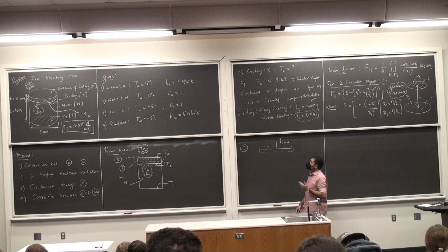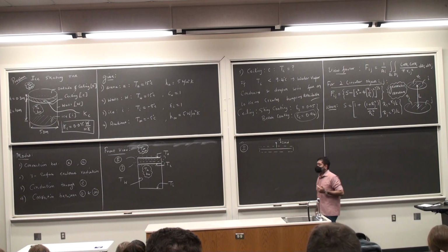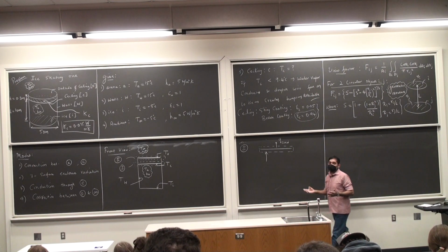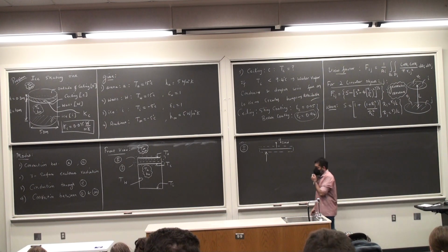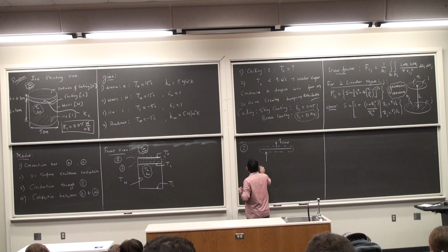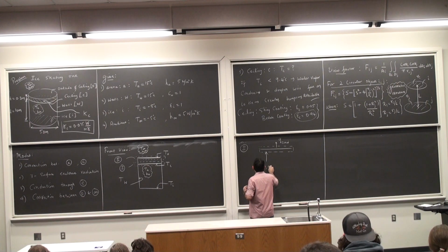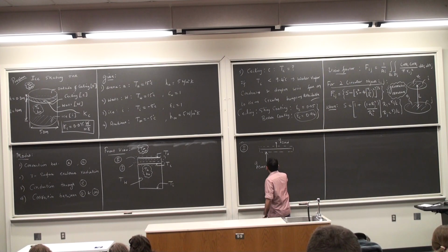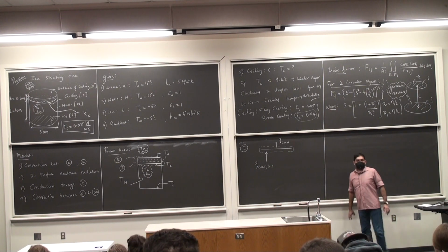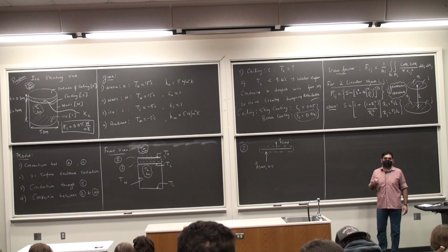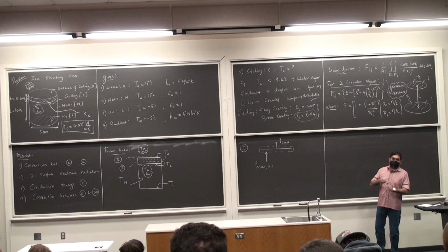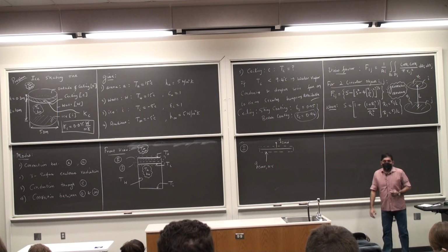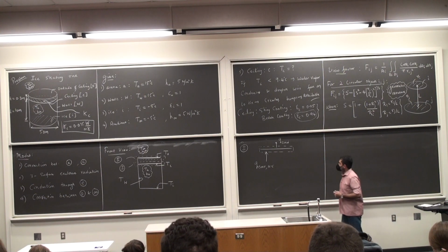Then maybe the ceiling is hotter than the arena air, so there is convection between the two. Or maybe the ceiling is colder than the arena air, who knows, really? So I'm just going to call this Q convection between A and the ceiling, so A and C. Is my nomenclature clear to everybody? All of the subscripts and so on. C for ceiling, A for the arena air, O for outside of the ceiling, infinity for the ambient conditions, I for ice and W for wall.